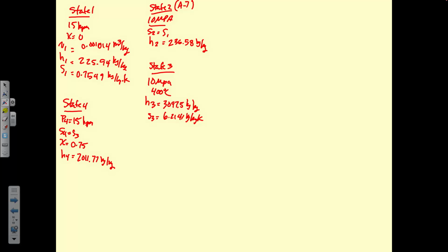We now need to find properties in the Brayton cycle, and because it's an ideal gas, we can't use the table. Well, we could use the tables to look them up, but we're given permission to assume constant specific heat, so we're going to use it that way.